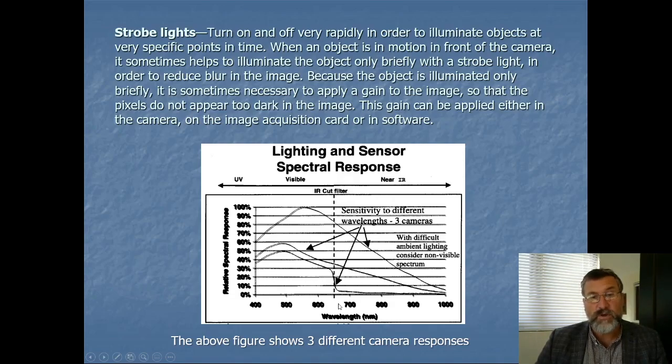But the problem was that we wanted to image the light here, so we didn't want this cutoff because we were trying to get a good sensitivity like this. So what we did, we took out the IR cutoff filters, but that altered the focusing of the camera. So we had to buy from Sony some dummy filters and put them in place of the IR cutoff ones, which worked okay, and they got it working in the States.